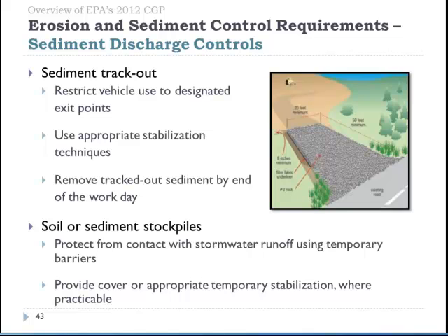So here the permit requires that vehicles be restricted to designated exit points so that they're not using an abundance of exit points that aren't necessary. Also to use appropriate stabilization techniques. And here to the right is a picture from our SWIP guide showing one technique. There's multiple techniques out there that are very effective at removing sediment from vehicle tires and preventing or minimizing sediment